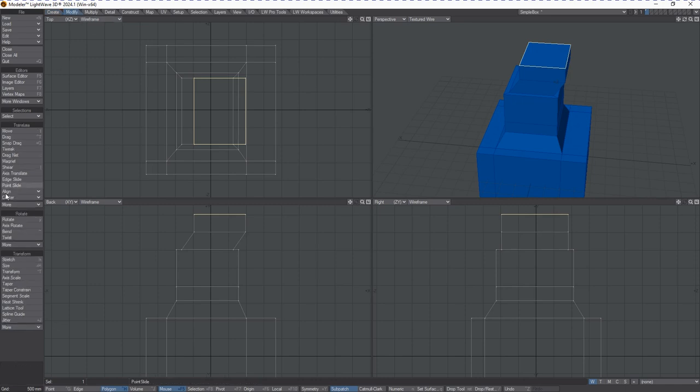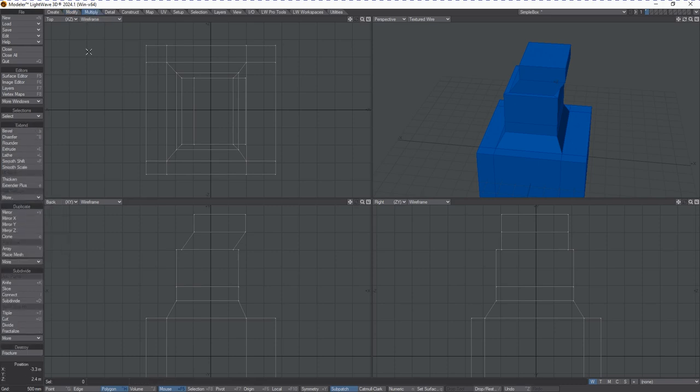And these tools are listed under here, under Modify, because once we've created a box, we can modify it, and we can modify individual polygons, we can modify the object itself. Move is technically a modification, drag, snap drag, tweak, dragnet, all these different tools are down here. And you get more inside. Multiply is where we get our B for bevel.